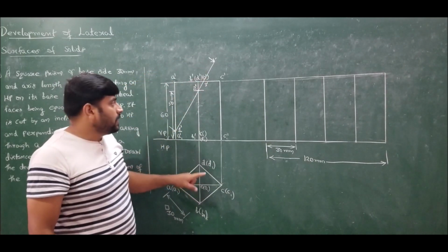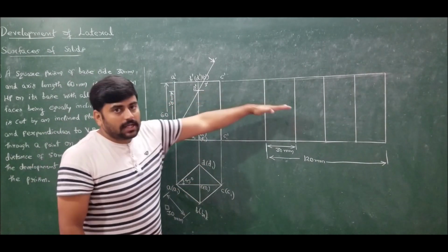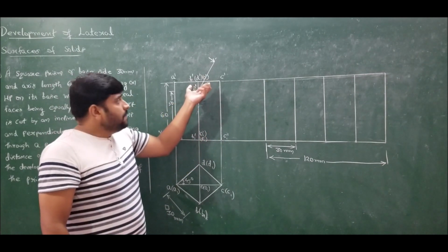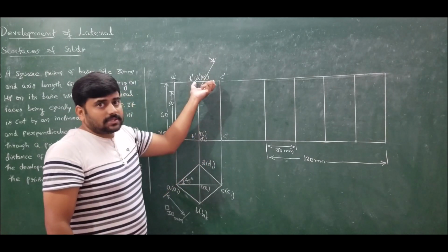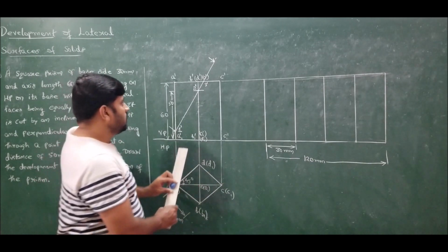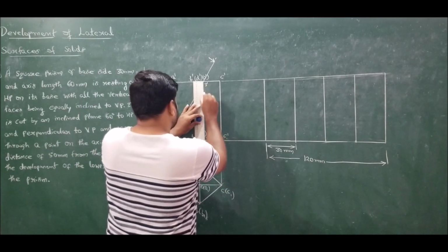Kindly make a note. If it is cut in the vertical plane, no need to worry, we can just take the parallel line. But if it's cut in the base edges, that is side edges, smaller edges, whether at the base or at the apex, then its dimension should be measured from the top view. So from 3 dash, you take projection again to measure the dimension.